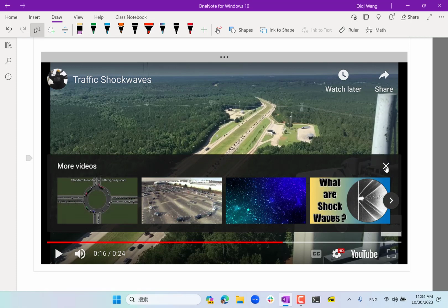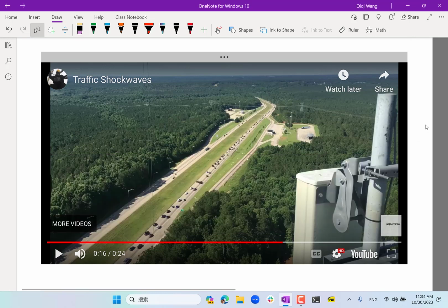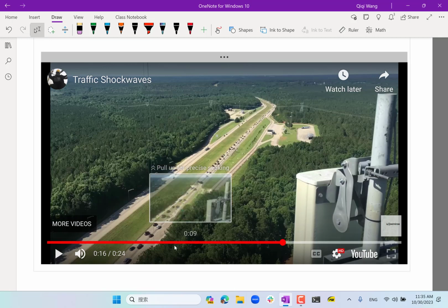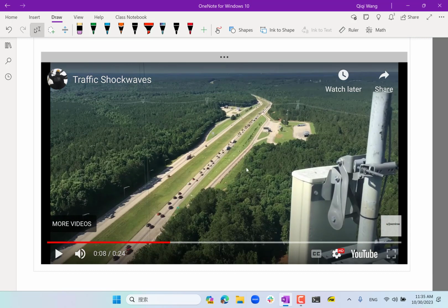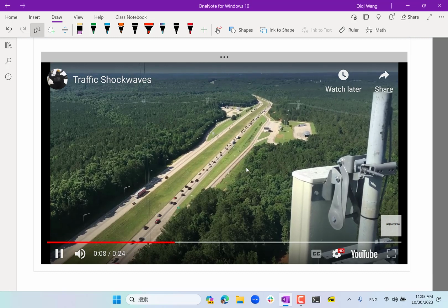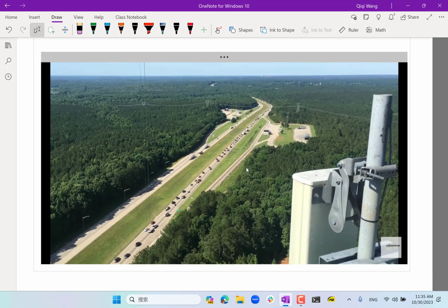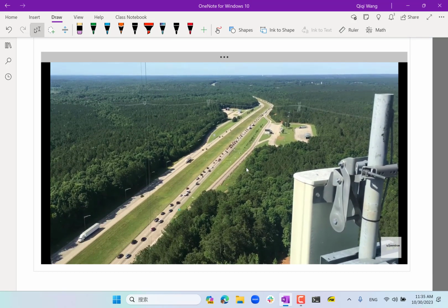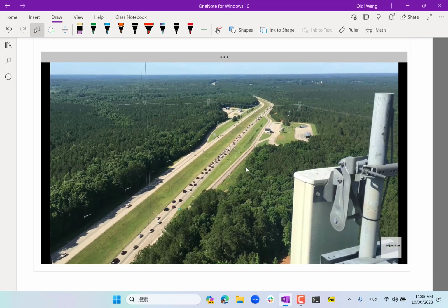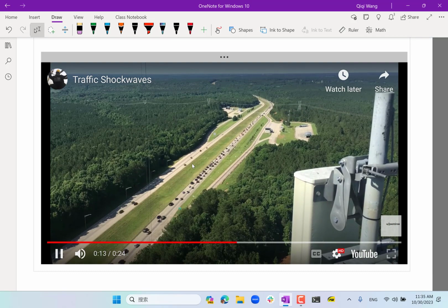All right. So basically the shock wave is like the boundary between a high density region and low density region of the flow. And in our analysis, we'll be taking a frame of reference not stationary to the highway, also not stationary to the cars. We are going to take a frame of reference that's stationary relative to this shock front and do analysis over here, right? Because if we take a frame of reference that moves with the front of the shock, we can do steady state analysis, and that makes our life a lot easier.